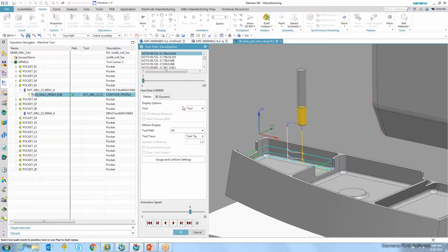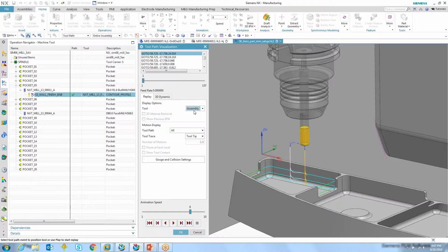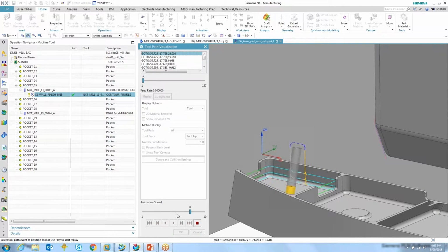So here we are. We have two things here. We have the actual solid assembly of the tool. What NX uses for the toolpath creation, and this is standard with or without MRL, is this: if you use a solid cutter that you imported, NX always uses a parameterized tool to create the toolpath because the math is easier. It understands the very specific diameters and things like that from the parameterized tool. And we can see that go around from the parameterized tool. But just like you would unmanaged or managed, doesn't matter.